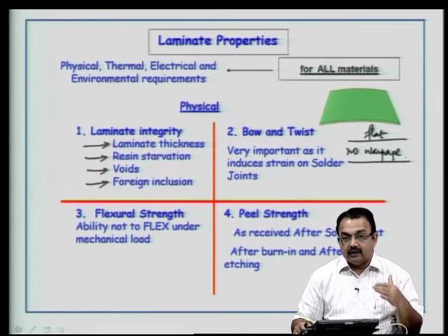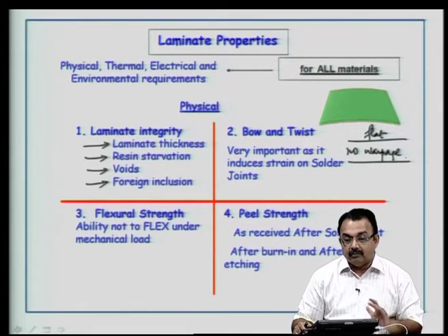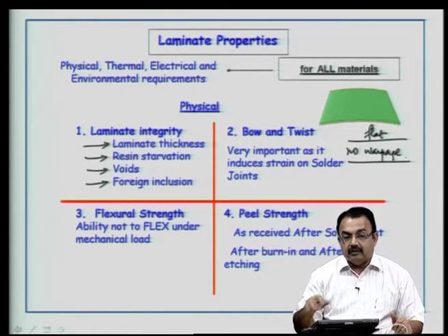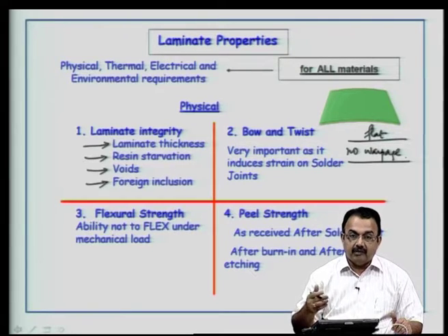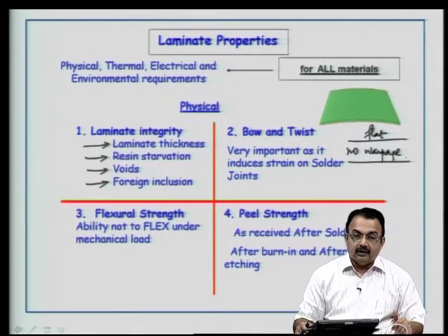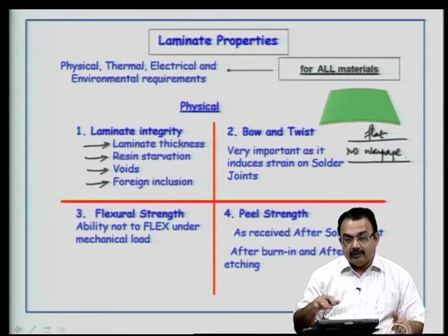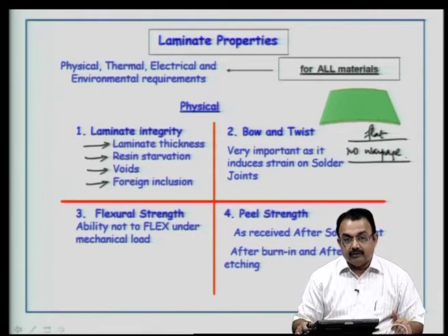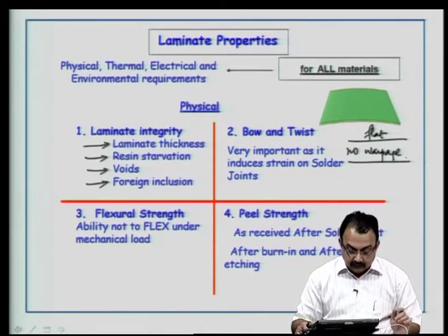of the correct thickness of the dielectric and the copper on both sides, if it is a double sided board. Now, if there is a bend and if you have started fabricating the PCB, when the board experiences thermal shock during soldering and so on, there will be dimensional changes, there will be heat shock, thermal shock, and this will induce the strain at the solder joint because of this warpage. So, make sure that your PCB is flat.